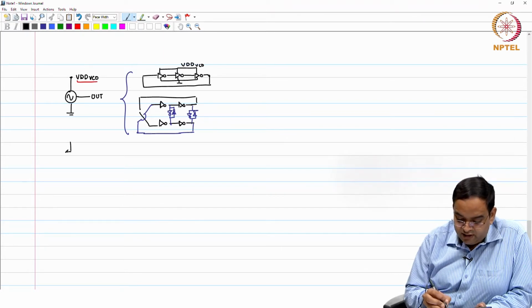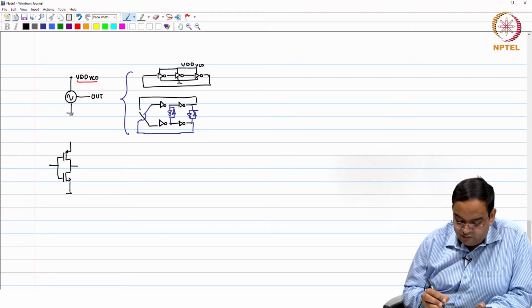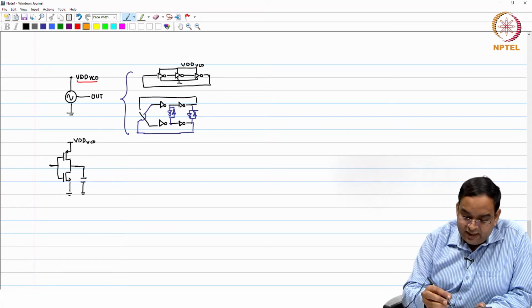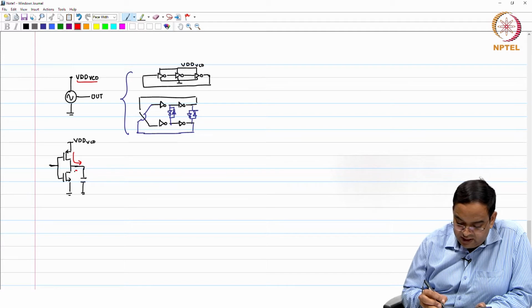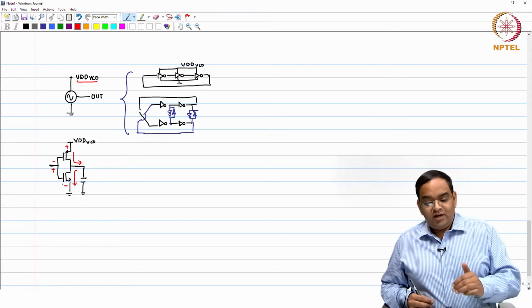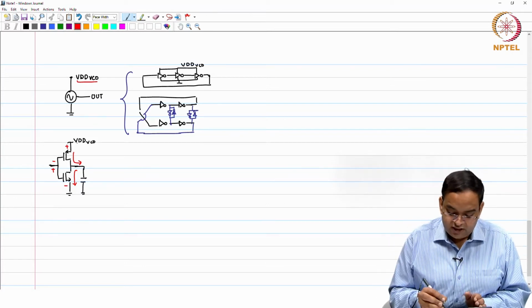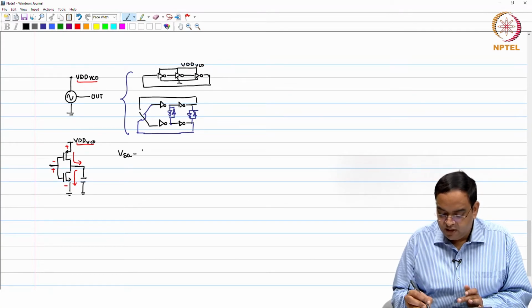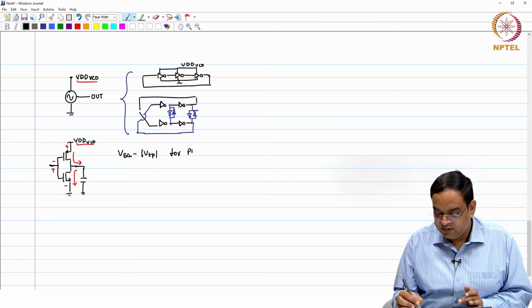because we know that when you have designed an inverter and you have this voltage as VDD VCO, the parasitic capacitance which you are going to have is fixed. So, the charging rate through the PMOS and the discharging rate through the NMOS depend on the gate overdrive for PMOS and similarly the gate overdrive for NMOS. Now, these gate overdrives depend on the supply voltage. When I say gate overdrive, it means VSG minus mod VTP for PMOS and VGS minus VTN for NMOS.